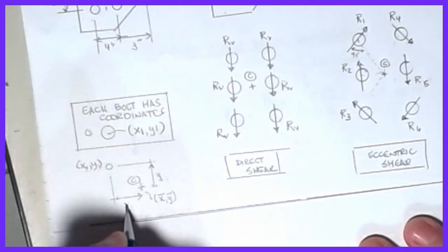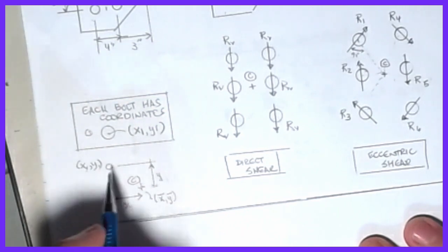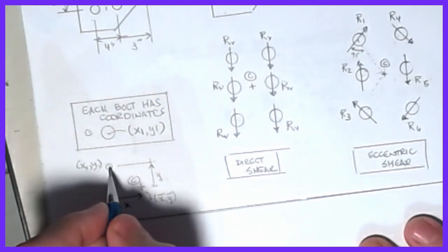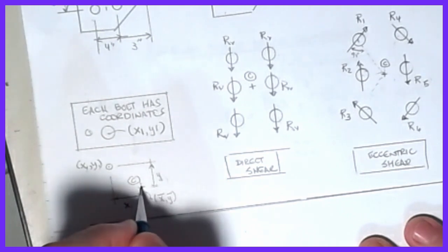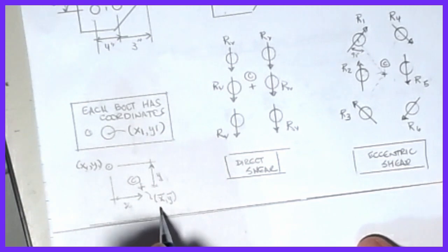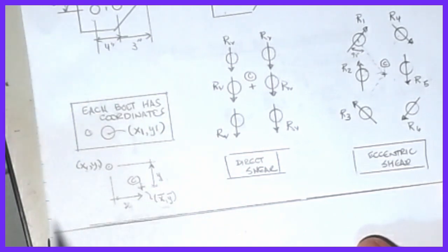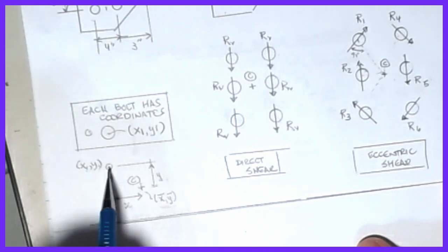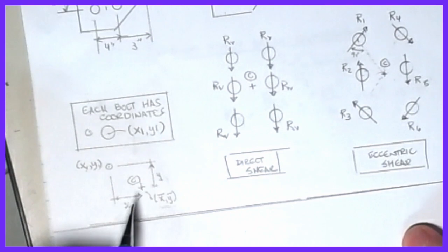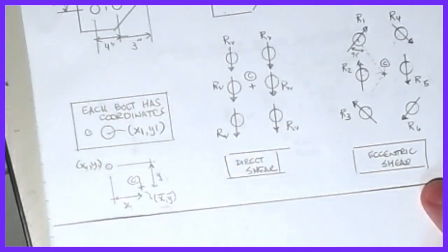then we're going to define x as the difference between his center point and the center point of the pattern, and y will be the distance between his center point and the center of the pattern in the y direction. So you'll use your basic statics or centroid calculations to find those locations, and then I can plug in the coordinates of my bolt and come up with those parameters. And these parameters will be important in our calculation.